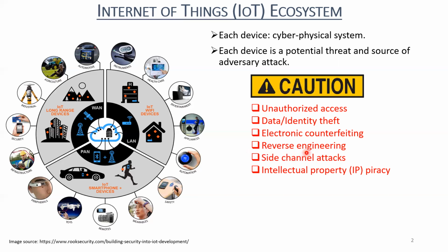So to prevent reverse engineering, nowadays what people are doing is something called circuit camouflaging. So what they do is they insert some dummy transistors, they insert some dummy interconnects, which are not actually doing anything, which are not providing any meaningful circuit operation, but are just to fool these attackers. So they just put some dummy transistors, dummy interconnects, dummy oxide layers, dummy deposited layers, dummy caps, and those dummy layers are just to fool these people.